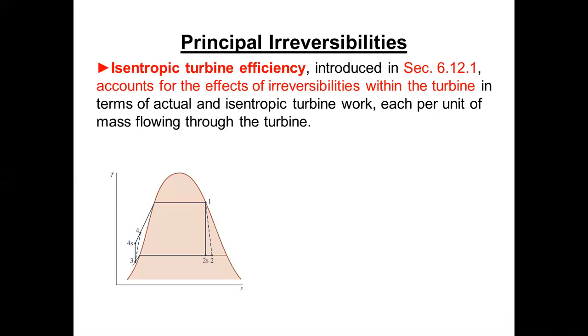Okay, and the turbines are also very low in terms of frictional and dissipative losses. When that steam turbine is spinning at 3,600 RPM in the States, there's no metal-to-metal contact. It is riding in the bearings. Oil flows through the bearings that support the turbine, and as we pick up speed above something like 1,400 RPM, there's no metal-to-metal contact.